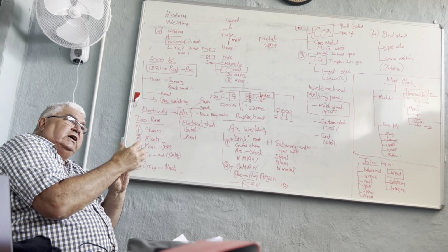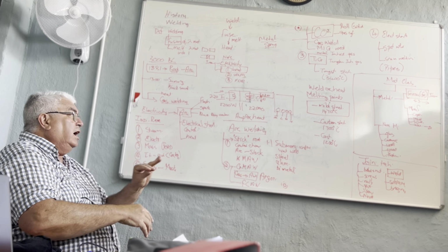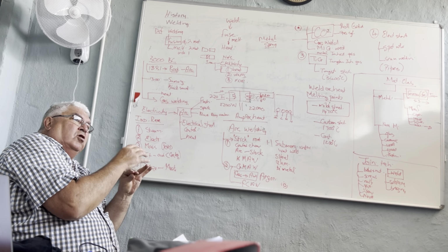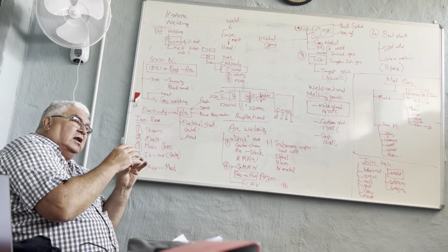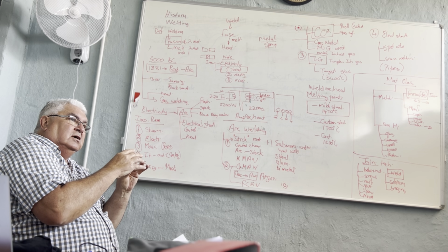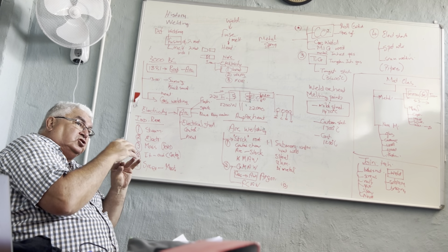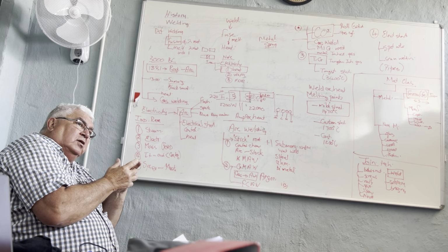Thirdly is your own protection. Eye protection, head protection, body protection. Any of these rays, if you don't have the right PPE, you are screwed. You can get arc eye, you can get serious burns, you can have many things. So the welding safety equipment is special, it's fire resistant, very durable.